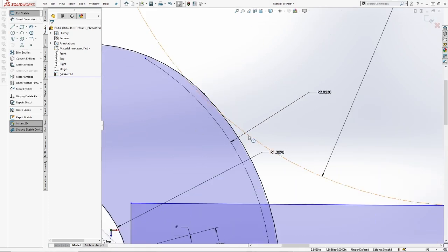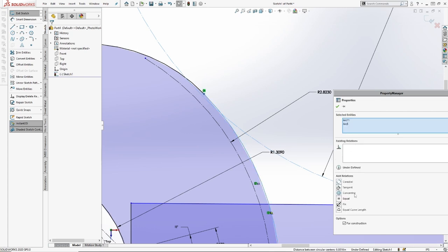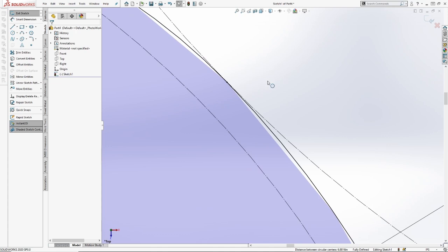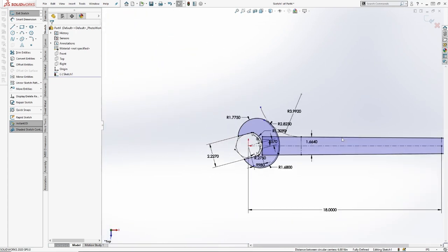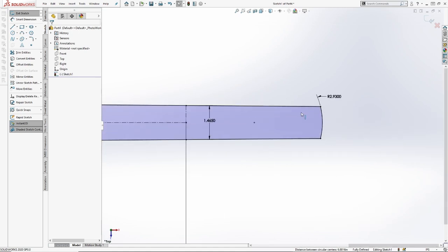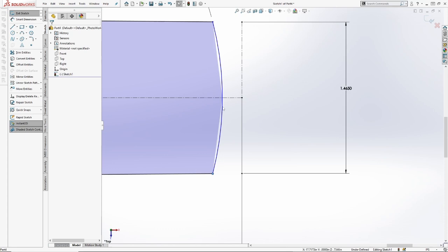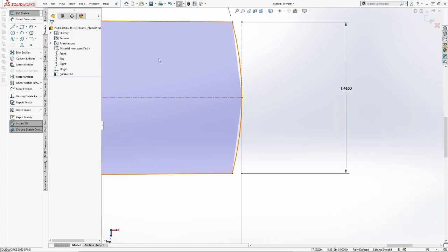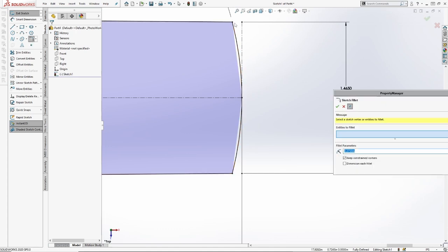And I'm going to just make it tangent to this one right here. Like I say, this line is sometimes going to fall tangent here, sometimes it's going to fall tangent there, so we can't include it in the sketch. Now we're defined, and we can... I see what happened. We tied to the wrong end of that arc. Now we're right. And there was a value down here. I was going to go with 0.125.